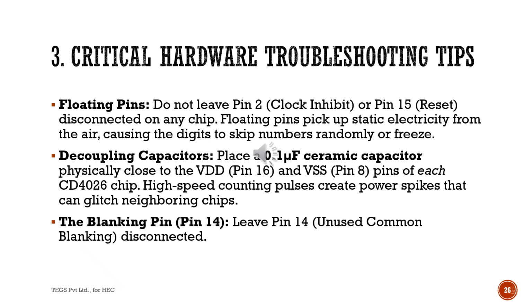Critical hardware troubleshooting tips. Floating pins: do not leave pin 2, clock inhibit, or pin 15, reset, disconnected on any chip. Floating pins pick up static electricity from the air, causing digits to skip numbers randomly or freeze.